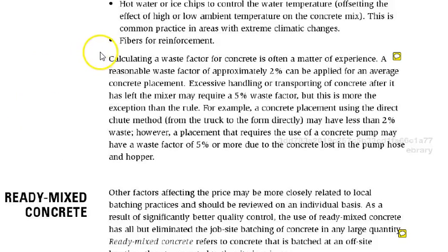There's a certain amount of wastage whenever you do construction work, and concrete is no exception, and you have to account for wastage. Generally, you're going to add about 2% for most projects. If you have to haul concrete a long ways, or you've got some special condition, you have to run it through a pump or something like that, then you may have a 5% factor.